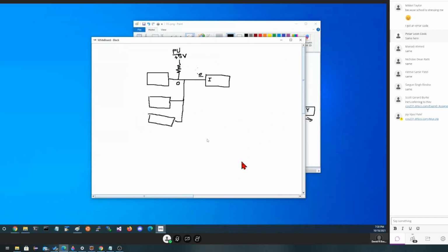Everybody kind of see how that could lead to us being able to have multiple guys writing at the same time? Now, that doesn't mean we're going to make sense out of what they said, because if all of them are trying to write 0s and one of them wanted to write a 1, the only way you can write a 1 is basically to release the bus, right? You just simply don't write anything, and you assume the bus is being pulled up. Well, it's not being pulled up if somebody else is writing, but no damage can occur. So we're on our way to being able to let multiple people hook up together. This structure of multiple people writing and multiple people listening, because we could have other guys over here listening as well, is called a bus.